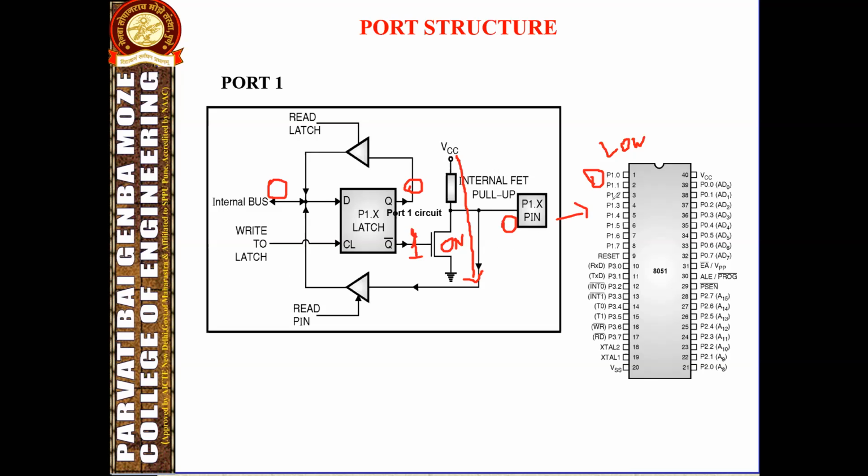What data or what operation is going on in these ports? How can we know? If we provide the read pin high here, the data here will be obtained using these pins. And one thing to remember is that the output of Q is forwarded back as a clock signal to this same D flip-flop. This operation should be performed like that.